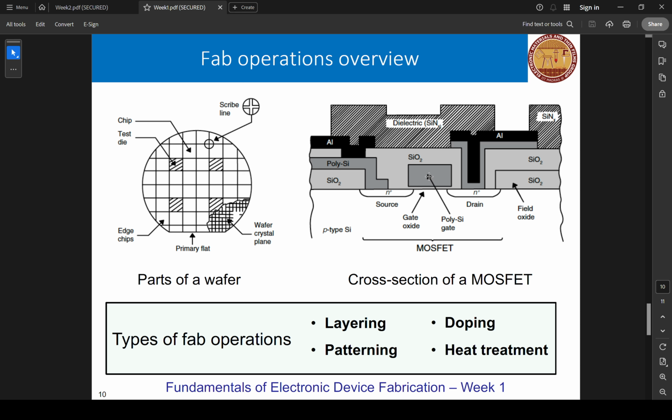Sir, normally when we operate the MOSFET, we will be having a drain source junction and a gate source junction. But here for silicon, they don't have any connection for the gate, as I can see from this. See, this is N plus, then here you have your polysilicon gate, which is very conducting. Like, doesn't the gate have any metal contact? How will they bias the gate in your picture? I don't know how, but they have a contact on the gate.